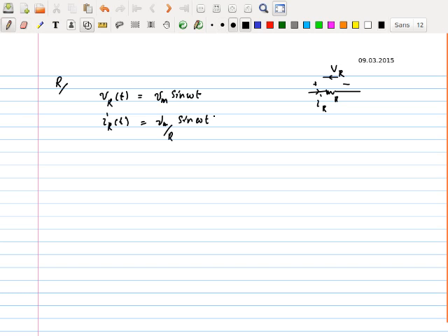So if I want to draw the phasor diagram for this, I have to convert this into R theta format. And you also know that if you are bringing from here to this point, you have to make sure it is the RMS value. It is RMS that you use as the magnitude, and the angle here, because there is no angle, is equal to 0.